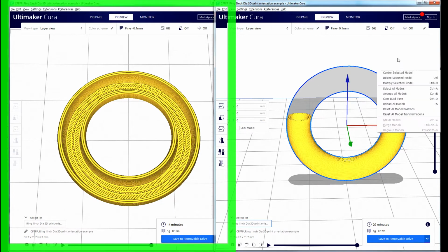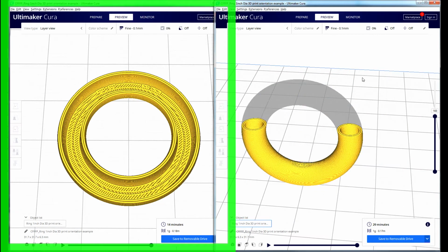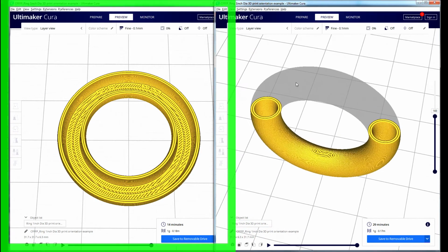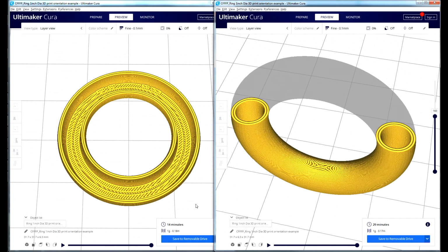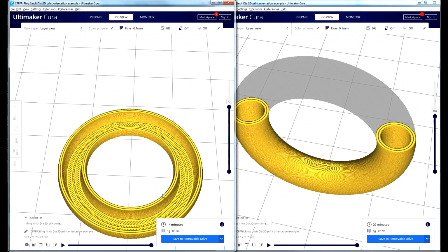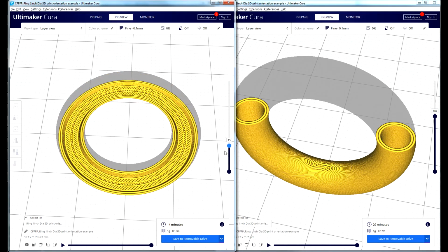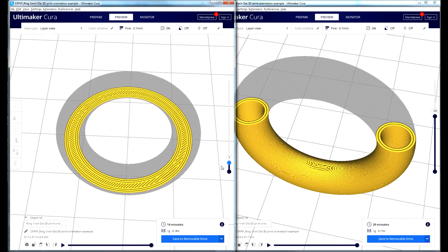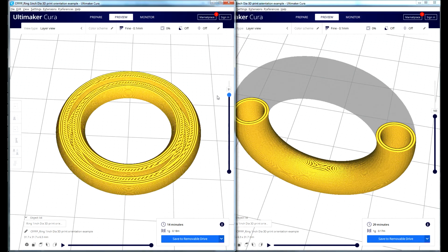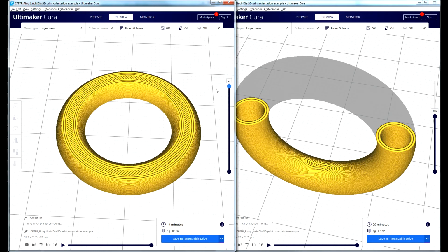Pulling the ring here results in a more resilient part, because the load is spread over a continuous strand of extruded plastic. This example is an oversimplification, but the principles still apply if you design and print a part that continues to break under mechanical stresses. If your 3D printed part is load-bearing or will experience strenuous forces, orientation will make or break the performance of your part in the field.